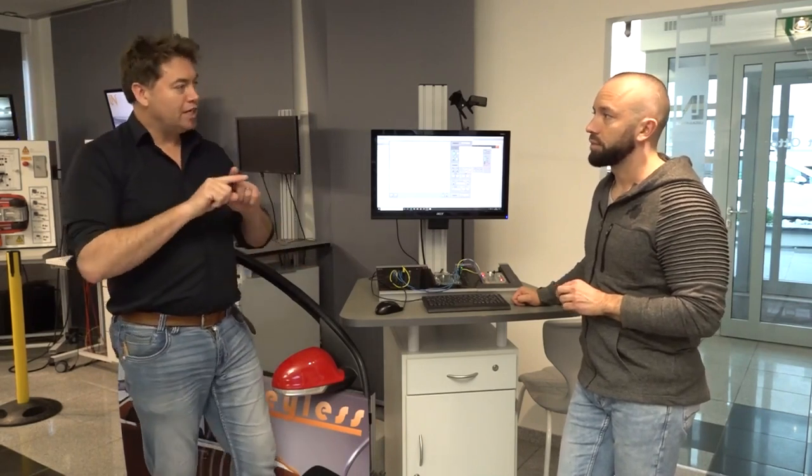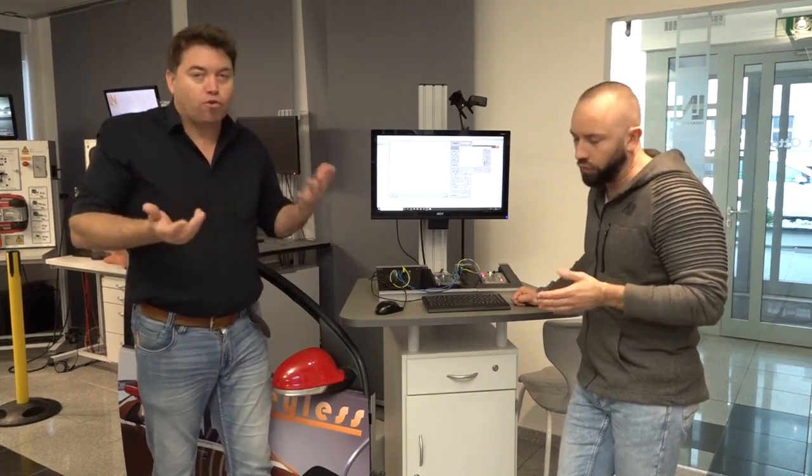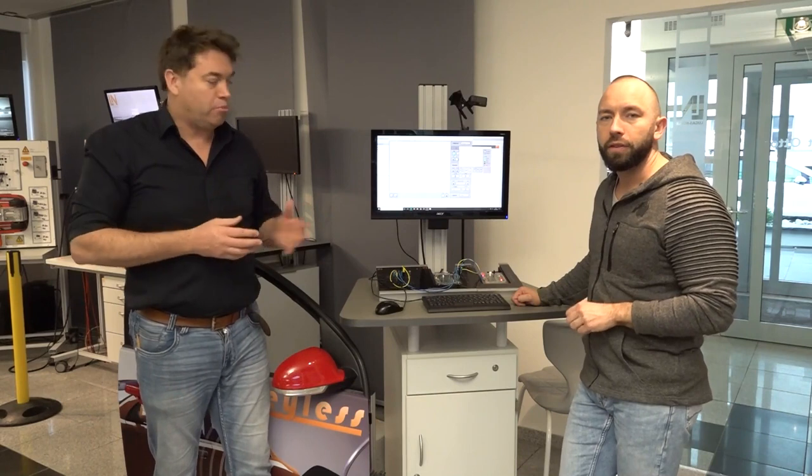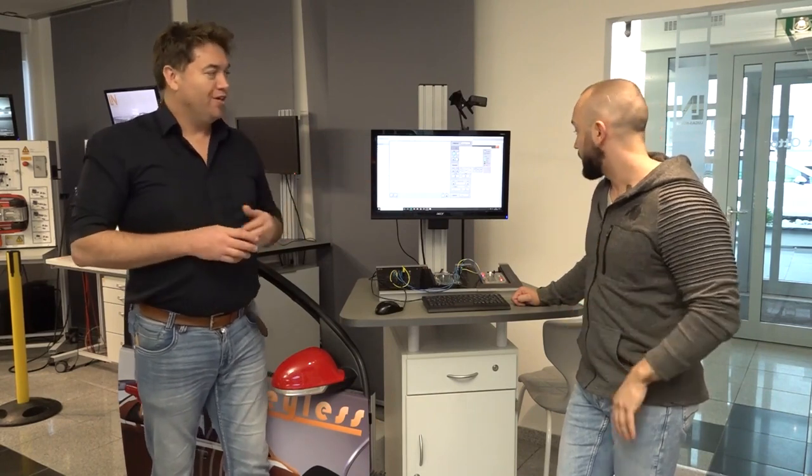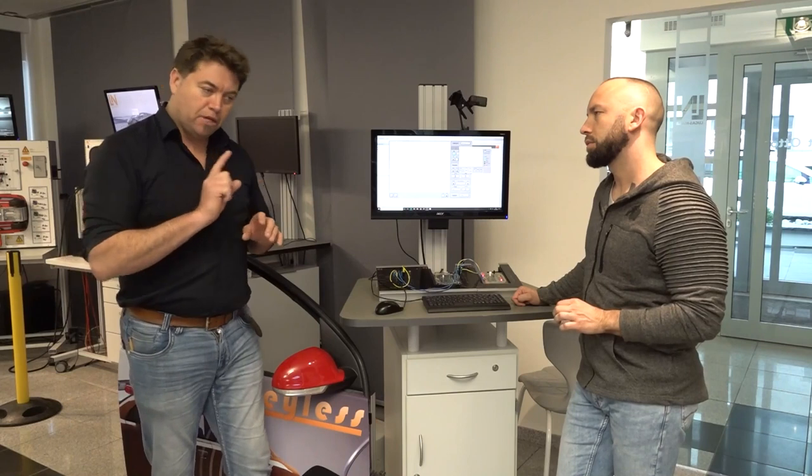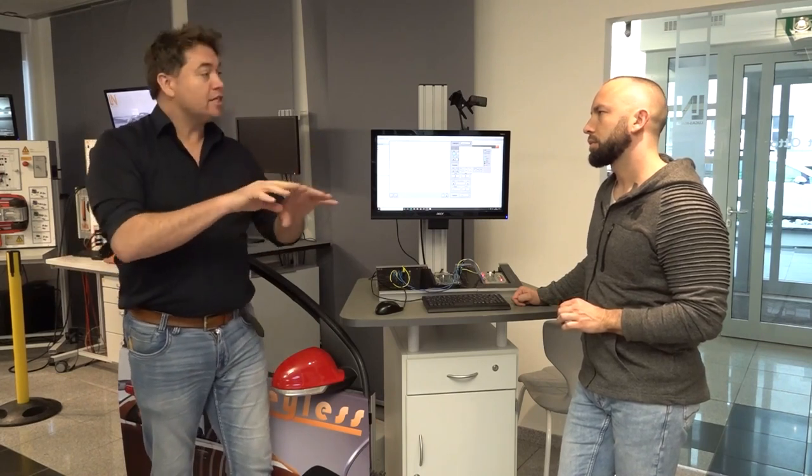Same goes for when it's sending a signal. You'll have a control unit in the back of the vehicle, so it's not sending this CAN bus message to the bulb itself. Obviously, the bulb is just on or off. It doesn't have any computing power. But no intelligence. Yeah. You mentioned before, Chris, the node. There are many CAN nodes. Each door has its own CAN node all around the place, and the message gets sent to that CAN node. It gets sent to all of the nodes, in fact.